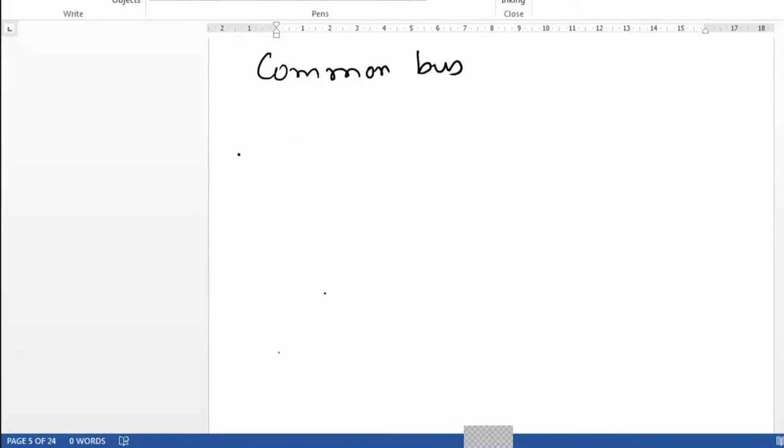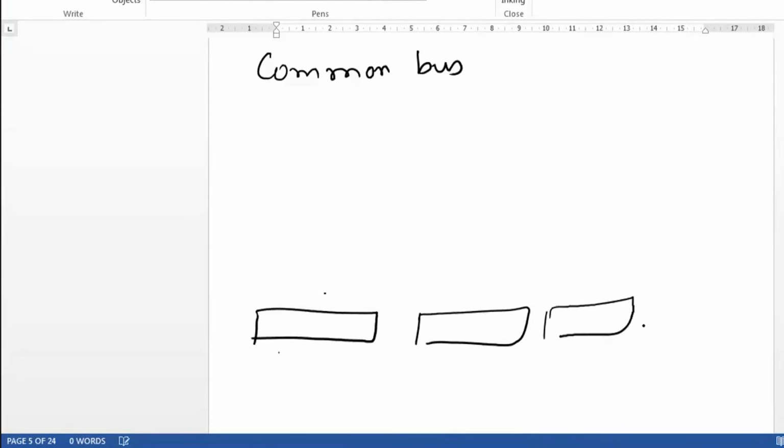Yes, gates, multiplexers, fine. You'll be using multiplexers. We know that if I want to carry out any type of selection, multiplexers are for selection. When I say that I want to carry out this operation, it means I want to select one particular register and only that data should go to the common bus. So I can simply use a multiplexer. So how to do that? Suppose you have 4 registers like this.